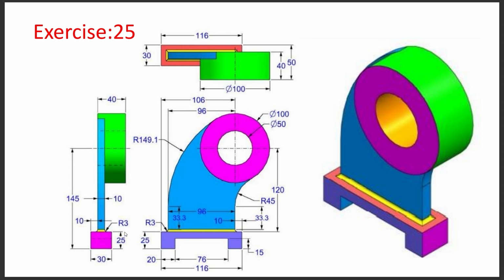Fine. So we need to provide different depth of extrusion. This one will be 10 millimeter, this is 40, and this one is 30 millimeter. And the extrusion will be started from different planes. From this one and that one, extrusion will be started from the base, and from here extrusion will be in two directions. If you are starting extrusion from this side, initially we have to extrude this one by a 10 millimeter in this direction, and the cylindrical portion to be extruded from here to this side by 40 millimeter, and for down portion we need to extrude this one in both direction. Initially that to be extruded backside by 10 millimeter and this side also by 20 millimeter.